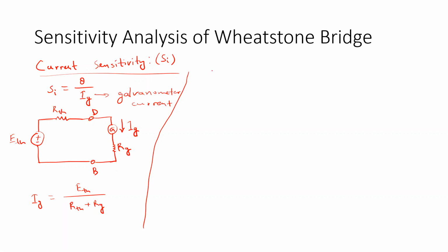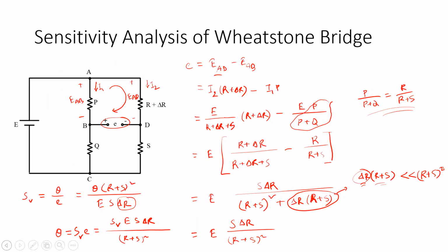Now for determining the Thevenin resistance RTH, we can redraw the diagram which was shown earlier. As our focus is to determine the Thevenin equivalent resistance across node B and D, we have to first eliminate the voltage source, and for eliminating the independent voltage source we normally make it a short circuit. So in this case node A and node C will now be the same node, and according to that we can redraw the diagram with respect to node B and D.